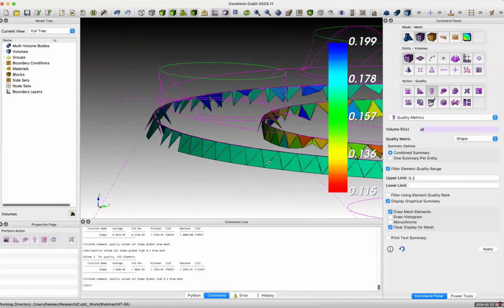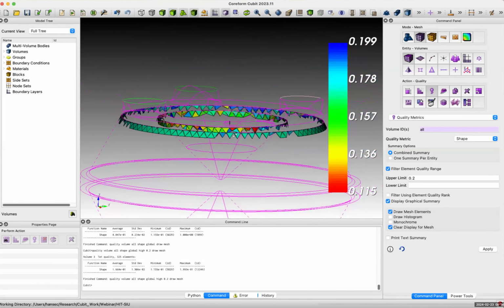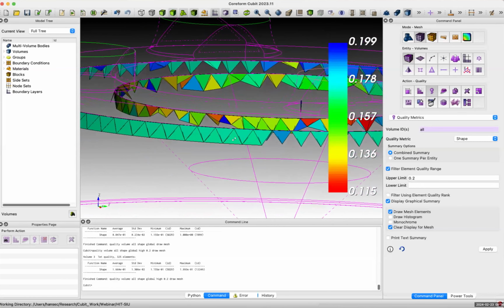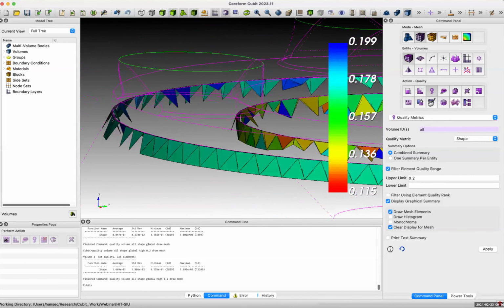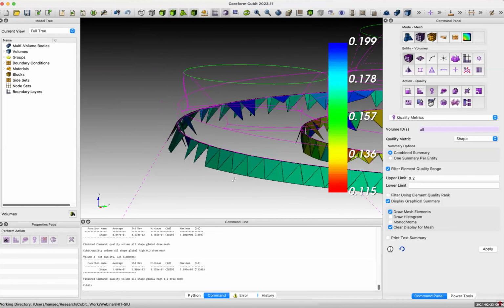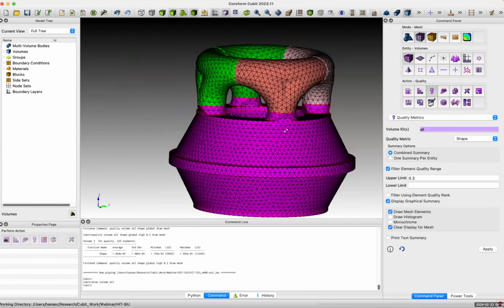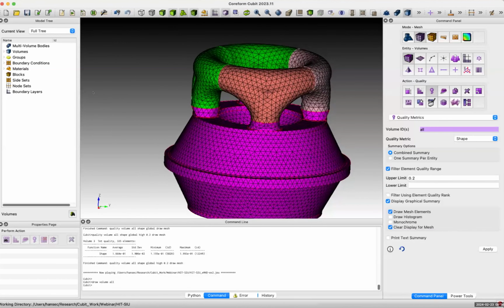So, again, this lets you identify this. Okay, this mesh looks pretty good except for these. All I would really need to do is go back in and redo that geometry to clean up this issue so that there isn't this tiny little surface here. And that should remove this particular case. So that is an example of setting up a complex 3D mesh like this.